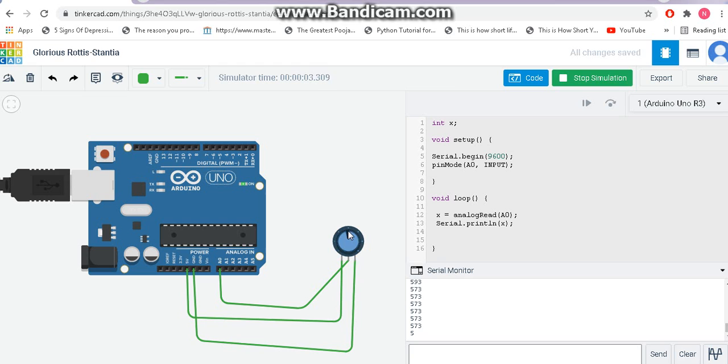I will make a small movement, again it is going down, right? Let's have somewhere here. So 511 is coming, so I am exactly at the middle point. Slowly I am decreasing. 409, decreasing again. 307. I will take my arrow out, that's why then only it shows. 205, 246, and at the topmost point it is 1. Actually it should be 0, but it is showing 1. Again, ignore this, maybe there are some simulation environment issues. But in your real Arduino, you will be getting zeros.